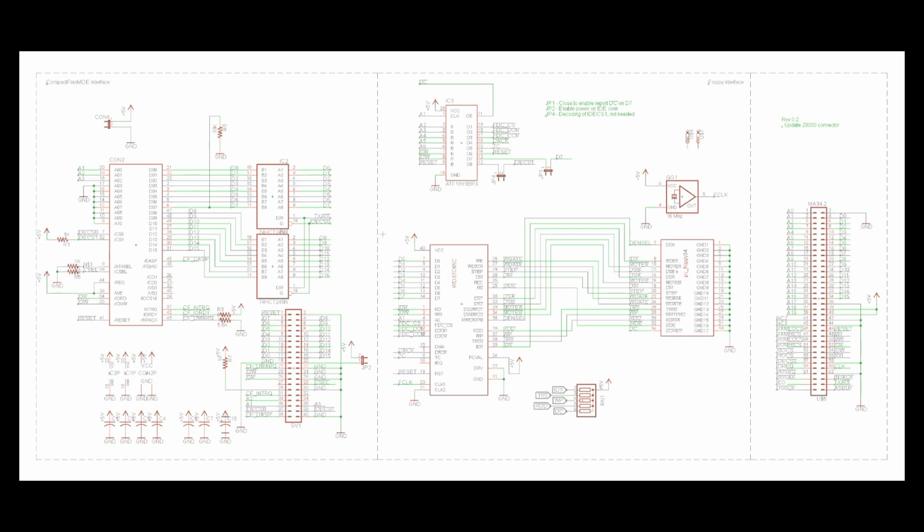Okay, here is the CompactFlash and Floppy board. So I think it's relatively straightforward. Over here we have the CompactFlash section, dominated by the CompactFlash socket, as well as a 40-pin IDE header in case you don't want to do the surface mount socket. You can use either one, but not both. Now, you could actually hook that up directly to the data bus, and some designs do. Back when I did one of my projects, like an XT IDE, I had some CompactFlash cards that would interfere with the data bus.